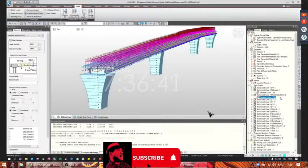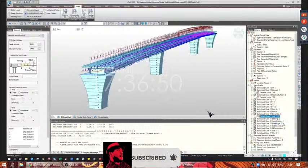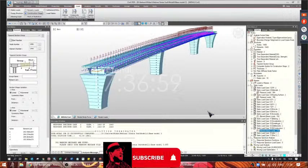The loads in case of execution are instead the beam loads. We created the concrete, the fluid concrete that is applied directly on beams, and the shear construction, that is the weight of the workers in casting phase.